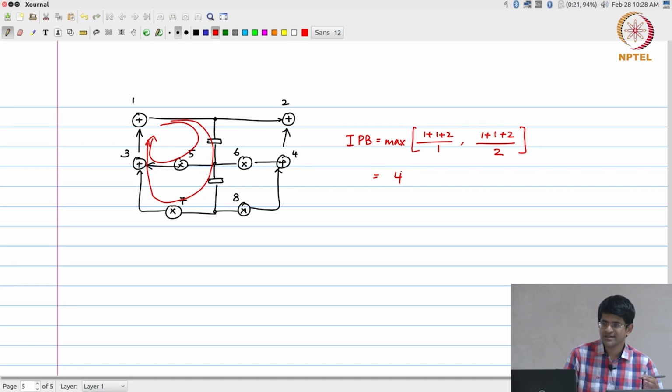The moment that you have a system, probably the first thing that you should look at is, given the hardware capabilities that I have, is there a limit on how low I can bring the critical path? Although critical path and iteration period are not the same thing, because I could have 2 parallel copies running, the moment I have a loop with a single delay element on it, I can't even use parallelism. Even if I try parallelizing, there is a fundamental dependency between one iteration and the next one, which means that the best critical path I can achieve is given by whatever is the limitation within one loop.